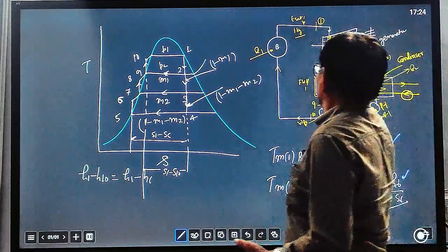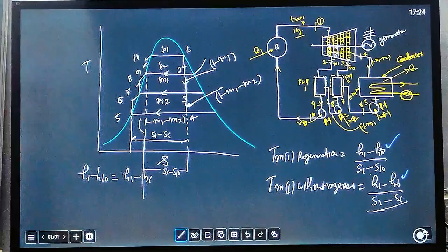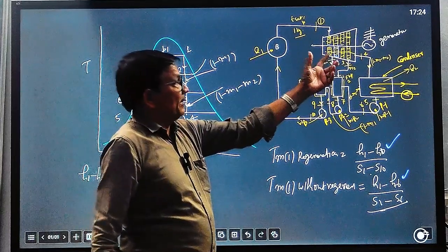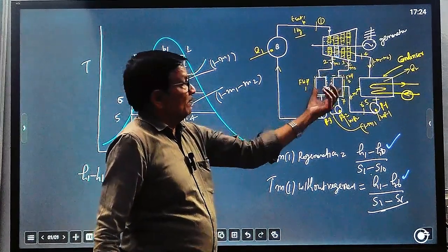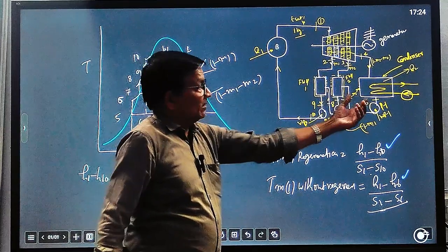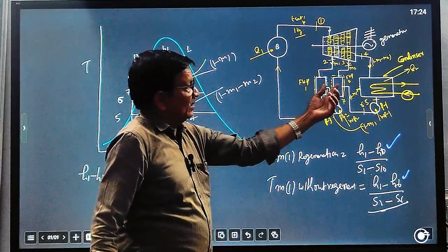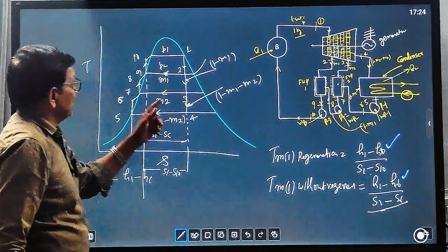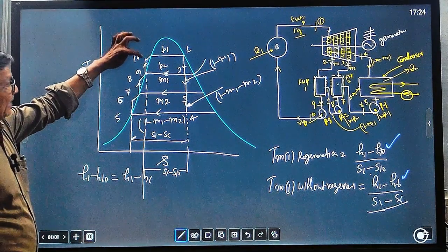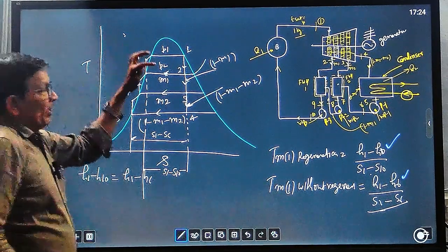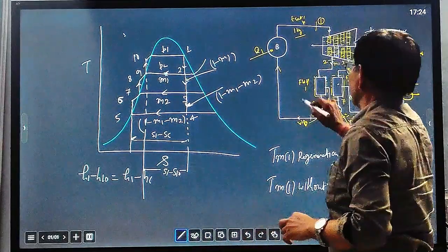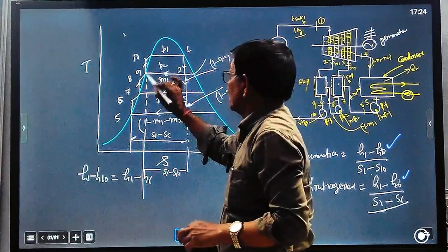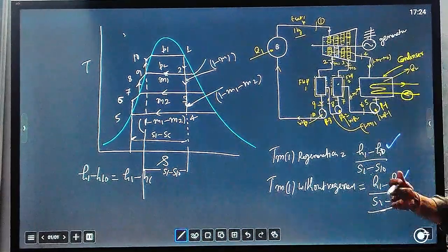So in this process chart, we have used two bypassings of a small quantity of steam, taken at state 2 and state 3, mixing with feedwater coming from the condenser at feedwater 2 and feedwater 1. In this way we have increased the temperature of heat addition up to 10. Finally, in the boiler, heat addition takes place from 10 to 1. Earlier, without regeneration, it was 6 to 1. So the mean temperature is increasing.